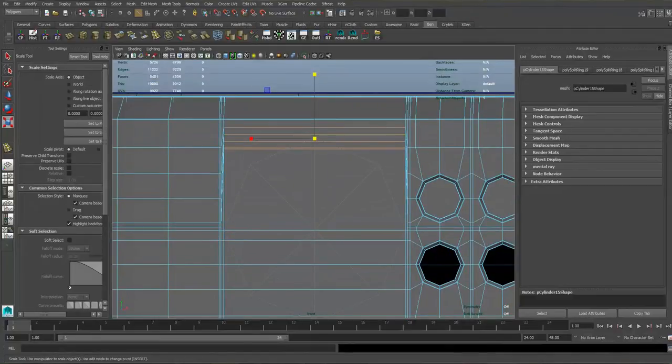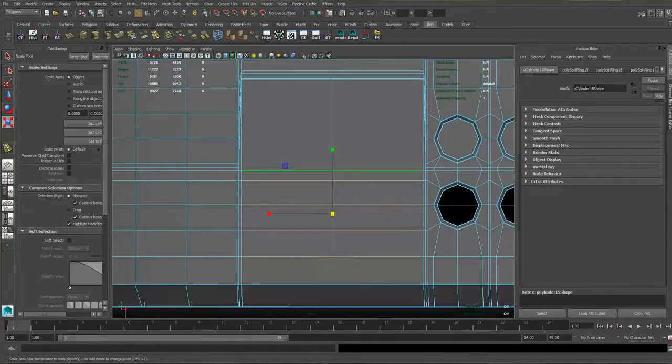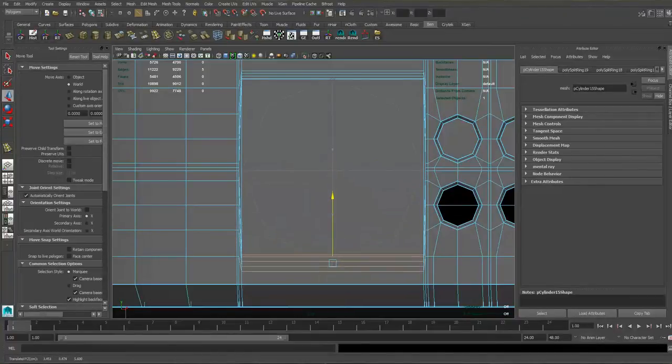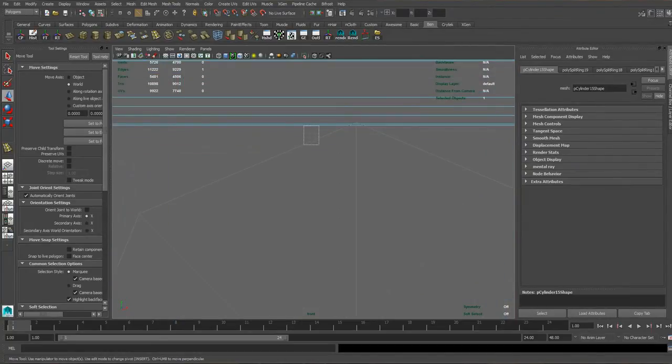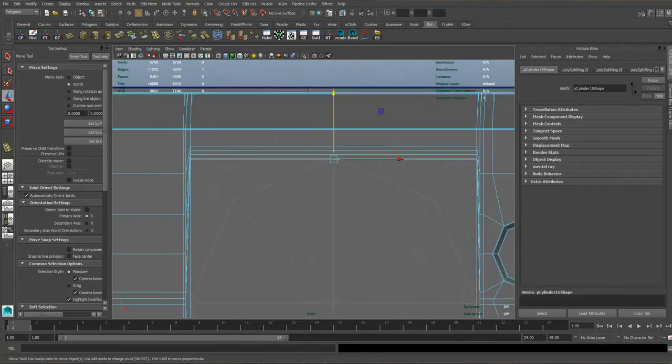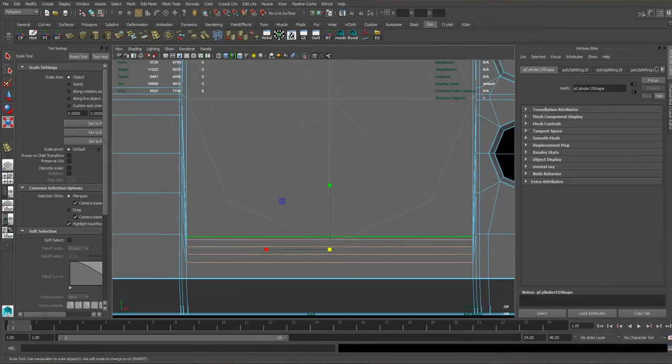I'm just going to resize these so they go around the top of the headphone jack like that. I'll leave them around about there for a minute. It doesn't need to be perfect yet. And these ones are going to go around the bottom of the headphone jack. So I go to edge mode, I have 1 edge, the bottommost one will be in the middle, and 1 at the top, and then just 1 at the bottom, and that's really it.